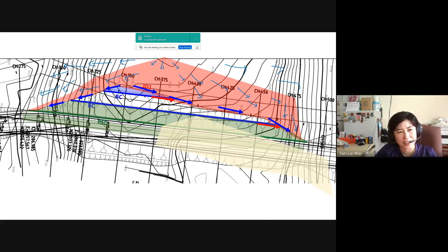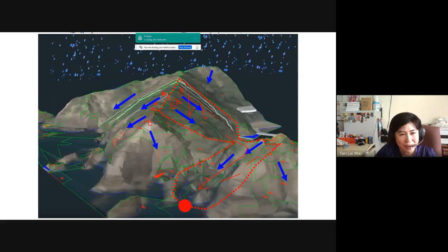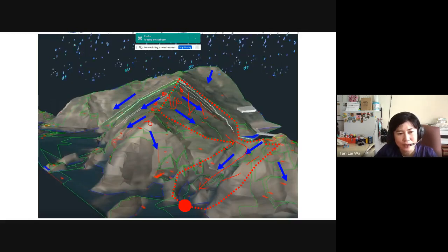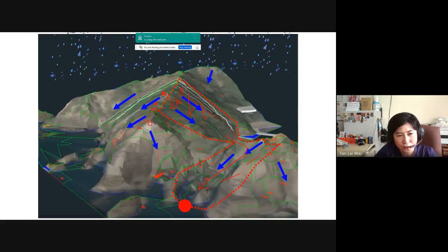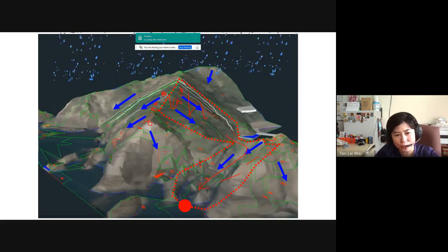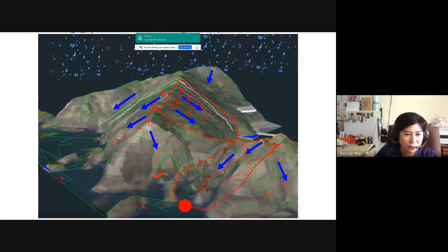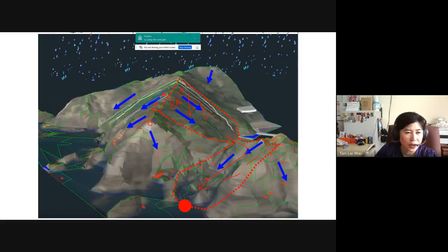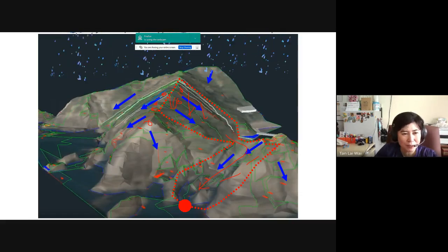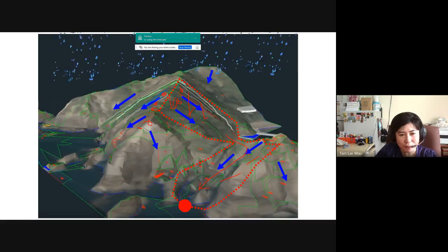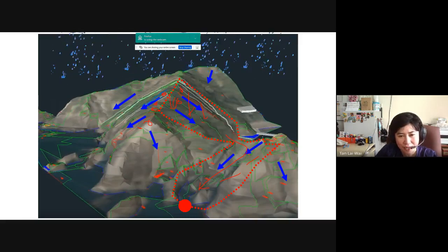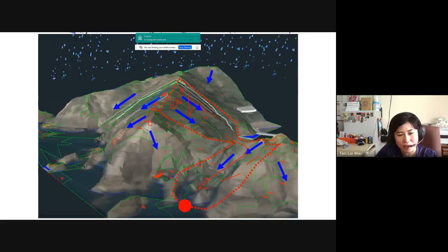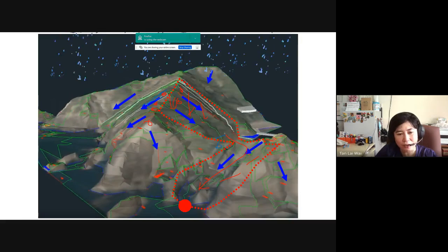Now by right, if you go back to this slide, look at this. This is the highest point. When rainfall falls on the other side, it will flow into the other side. And when rainfall falls on the left side, it will flow to the left. So that's how you determine this boundary. It's actually the highest point. For example, you compare left and right, this part is the highest point. We say it's the highest point because this will separate the direction of flow.